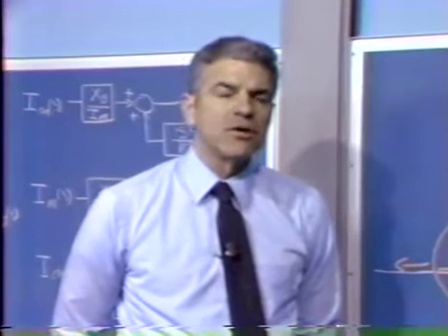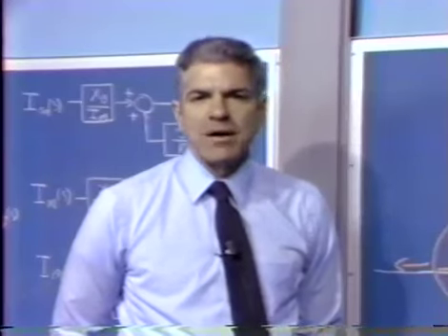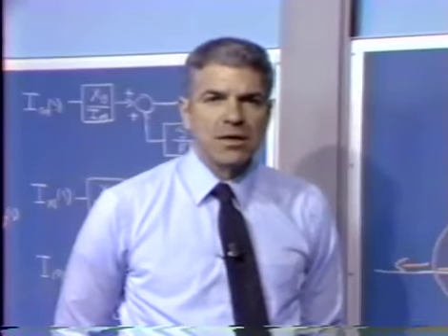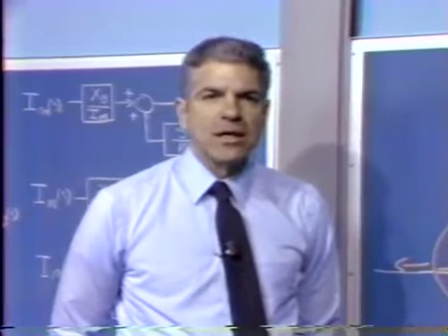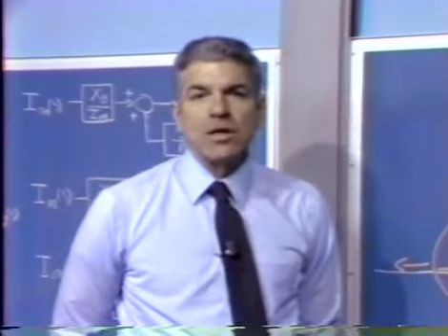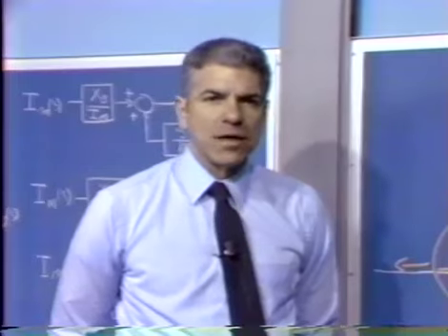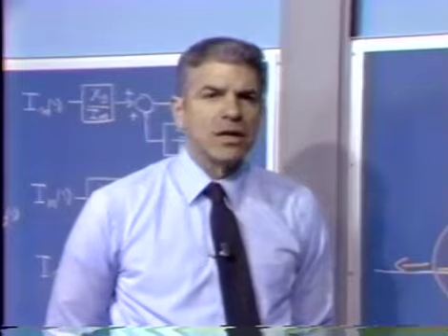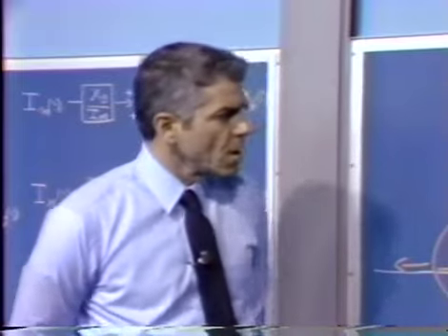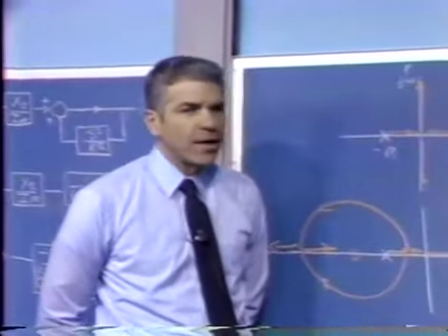The operating point here is chosen such that about half the photoresistor is shadowed by the ball. And again, if we did the analysis in great detail, we'd linearize the transfer relationship associated with that sensor, and it would simply become another scale factor in our set of equations. But there is a time constant associated with it.